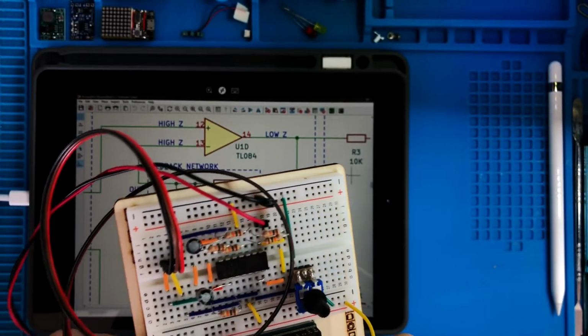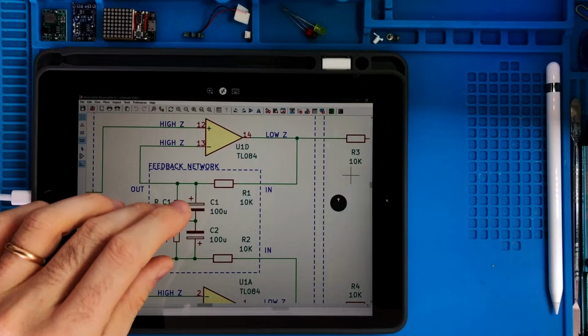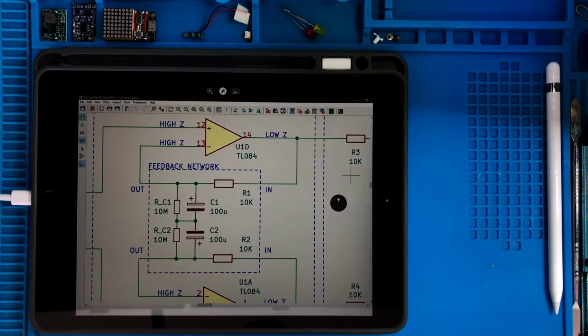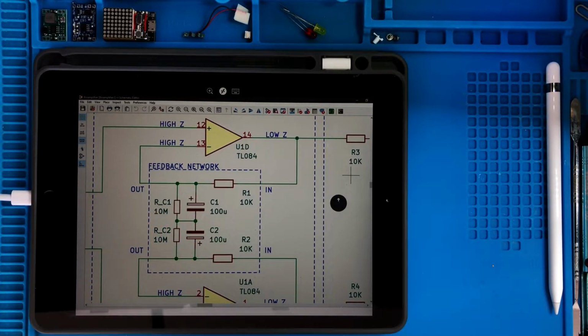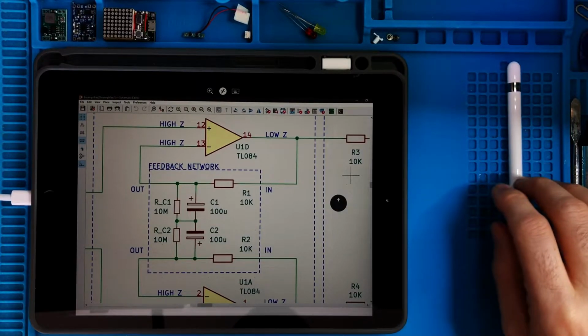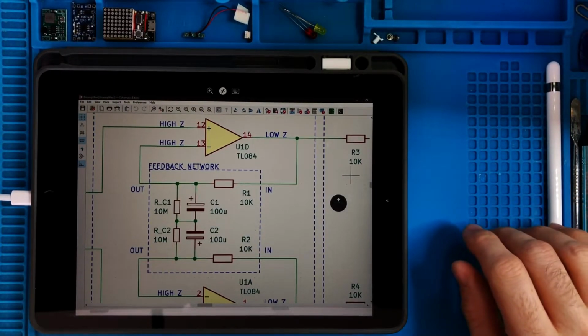So this is capturing the real implementation of the components, but of course the simulator doesn't know about the real components. The simulator is just doing mathematical calculations, so we have to include those parasitic components in the model sometimes, otherwise the simulation, as we say in the electronic jargon, will explode. To make a long story short, this is why we sometimes need extra components to make the simulation work in a more precise way.